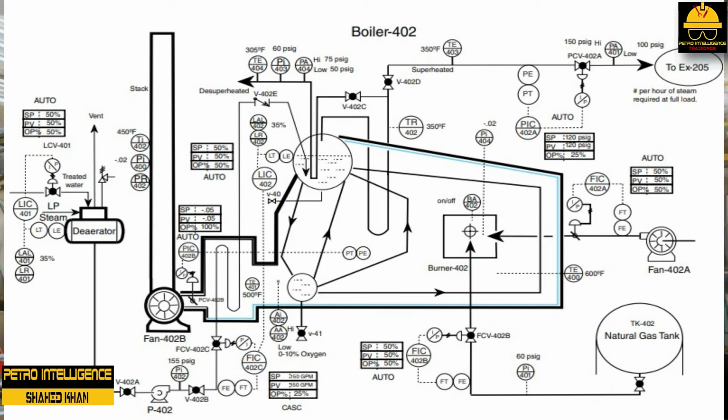One of the most important safety concerns is to establish water flow and drum levels prior to lighting off the burner. When the burners are lit, hot combustion gases begin to flow over the generating tubes, riser tubes, downcomer tubes, and drums. Radiant, conductive, and convective heat transfer begin to take place. Hot combustion gases flow out of the firebox into the economizer section and out the stack.